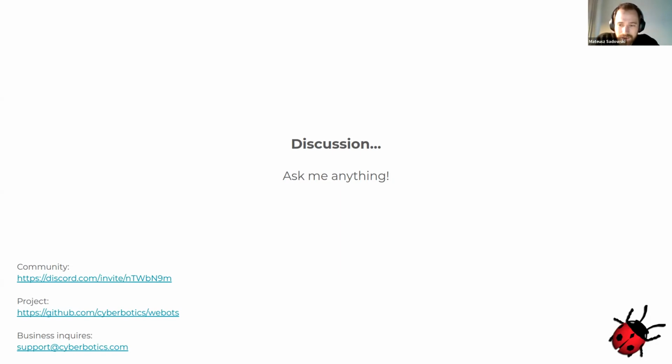Okay, let's see another question from Bruno. Great work. I also have a question. Does Webots have a motion planning environment, or do you guys use MoveIt for that purpose? It's MoveIt. We published a library, IKFast. So you can take your robot model from Webots, and it will generate analytical solutions that you can use for inverse kinematics. And IKFast generates solutions in a few microseconds.